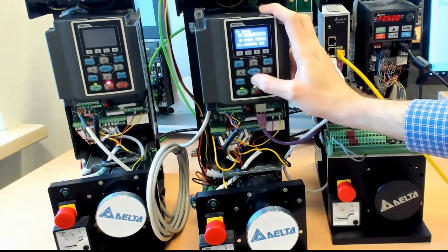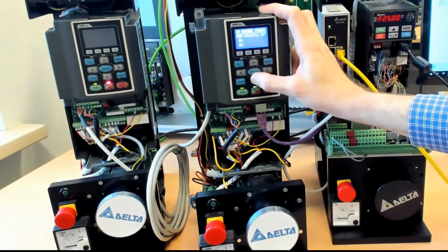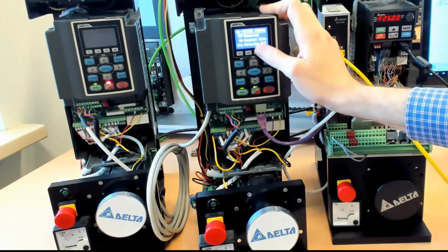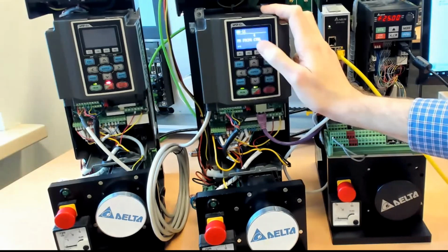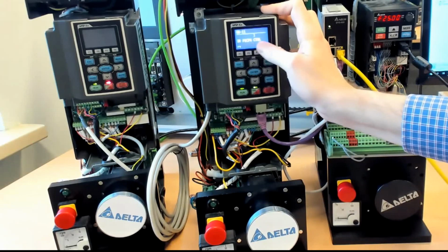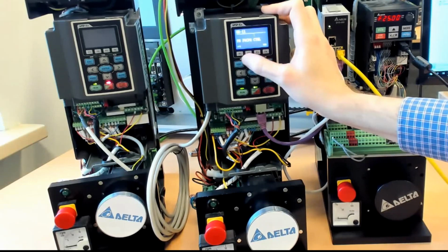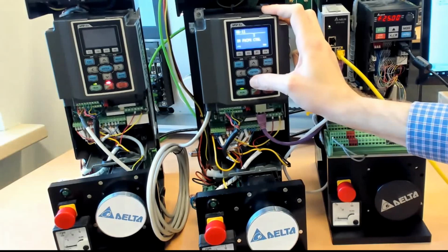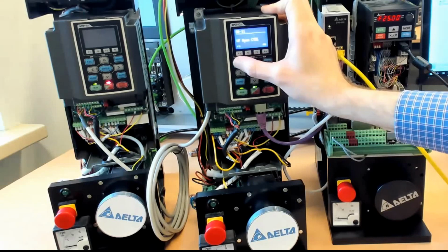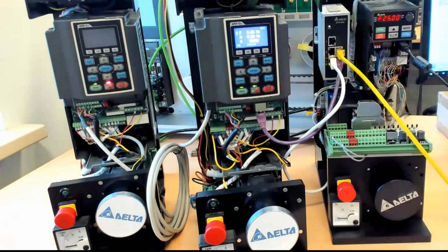So you can only really do positioning with these two modes. If you go to parameter 00-11, velocity mode, you can only really do it with 4 or with 3. So IM FOCPG or PM FOCPG. You cannot do it with any other mode. You cannot do it in SVC sensorless or VF. So it's mandatory to have an encoder. Okay, so I hope this answers the question.